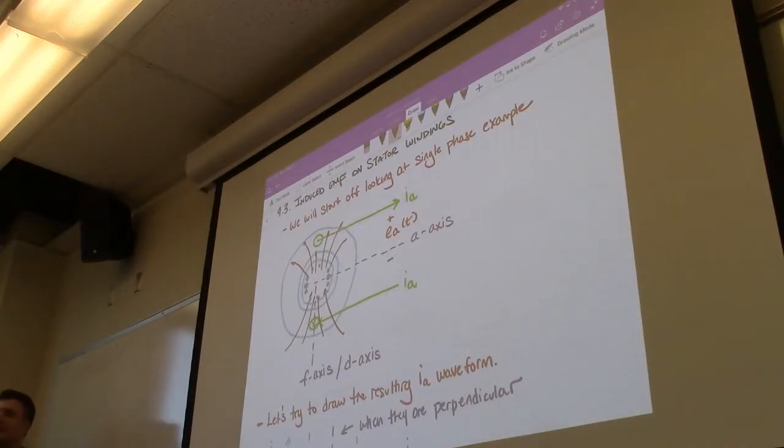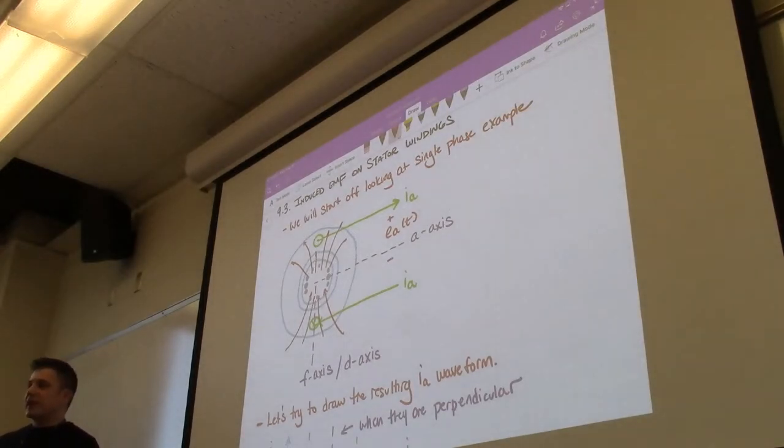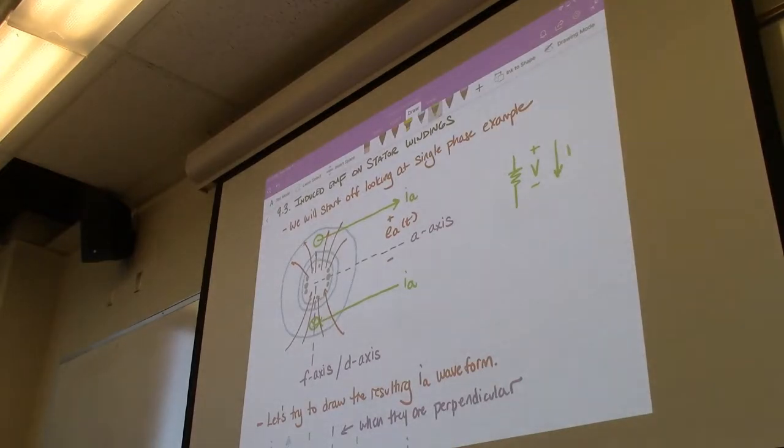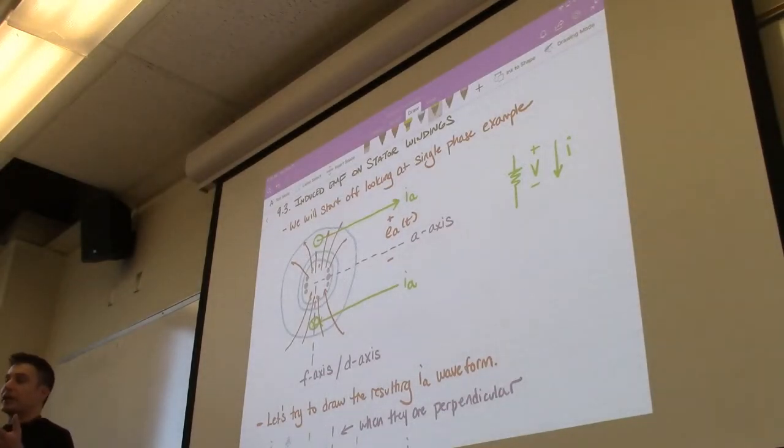Right, we have passive sign convention, which is for passive elements, right? It says that, if I draw it over here real quick, if you have a resistor and you have your V plus minus, your current runs in that direction. And then for active elements, things that are injecting energy into the system, we often use the opposite, right? Where we assume, like for a voltage source that's injecting energy into the system, the current flows in the other direction, right?